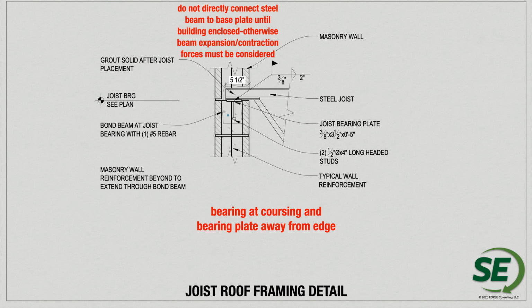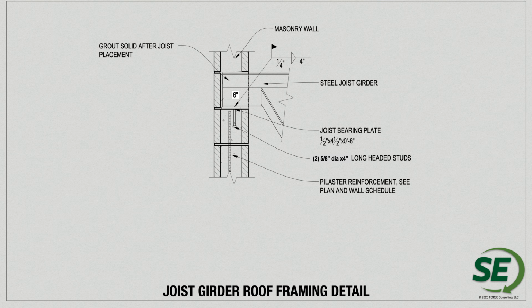Also, we want to be very careful when we connect steel to masonry, and what the masonry does. Does the masonry have the ability to flex or move? Because steel, again, as the thermal loads from steel framing into masonry, steel is going to change size quickly, and we need to make sure that we have some allowance for that in construction.